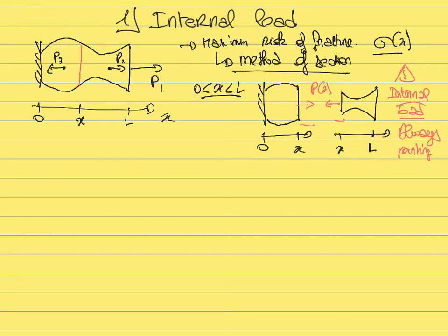And if you have a left surface, then the load will be pointing towards the left, always towards the outside of the material. Keep in mind that this doesn't tell us anything about the sign of the projection of this internal load. If we take this load on the right surface, it's going to be pointing towards the positive x, so it's going to have a positive projection.